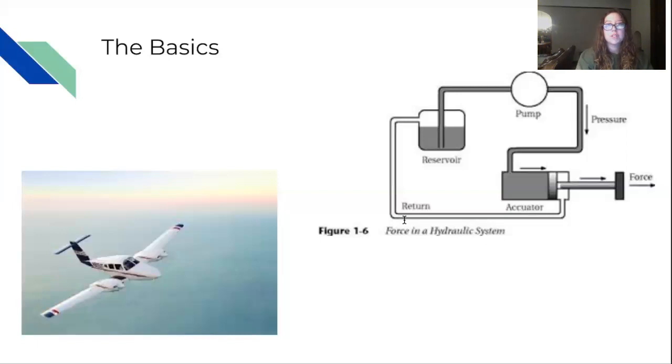Pressure control valves are another important component, and these can either be a pressure regulator valve or a pressure relief valve. The pressure regulator valve senses pressure downstream from the pump, and if it exceeds a level that has been set by the manufacturer, it sets off a spring and a valve opens to recirculate the fluid outside of the pressure control area for reuse. The pressure relief valve is usually only used as a backup system, and if it senses a higher than normal pressure, it will open a release valve.